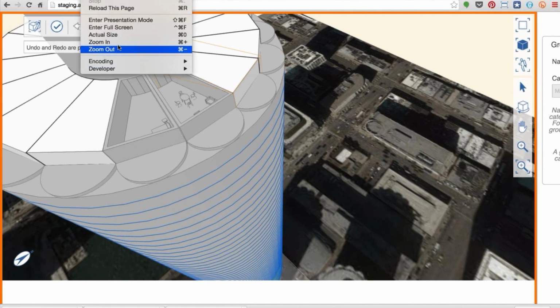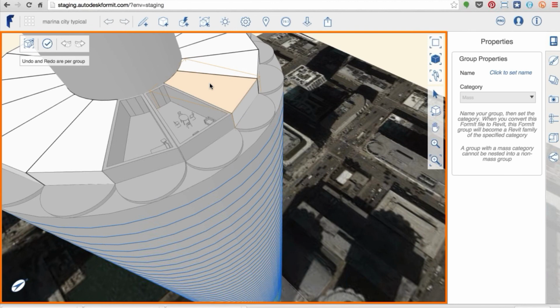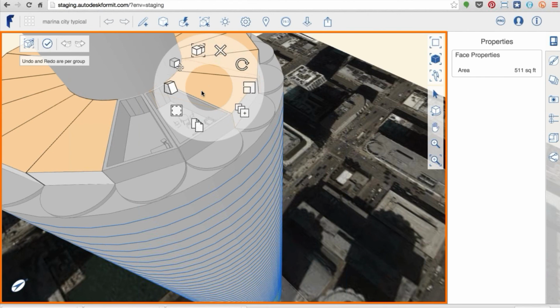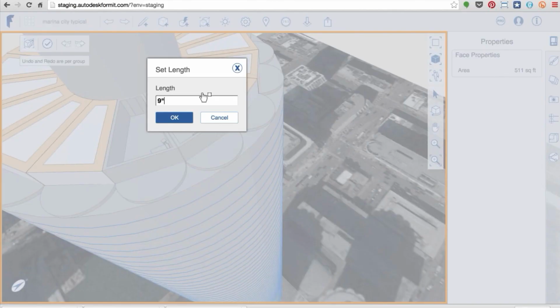Is that how you created those walls, Tom? Yeah, exactly. That's a great segue. Yeah, totally. Let me get my zoom back here. So that's exactly how I made these pseudo walls. I'm in this group, and if you right-click on any face, you choose this Offset tool or use the OF keyboard shortcut, and then you press Tab to set a specific